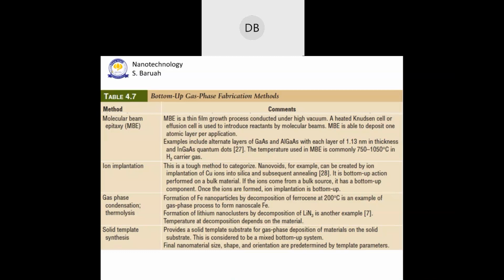That's why most of the techniques adopted for making integrated circuits have already been experimented with to make nanoparticles. Ion implantation and molecular beam epitaxy are some of those, and in integrated circuits we normally use a lot of gallium arsenide, GaAs. Those processes can go very low; the thin films we make can be even 1 nanometer or just above 1 nanometer in thickness.